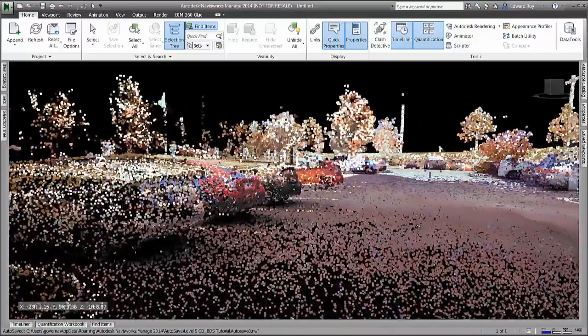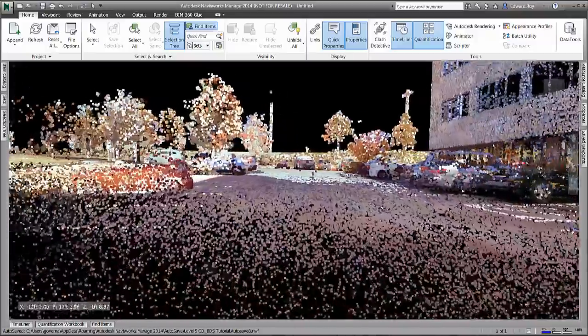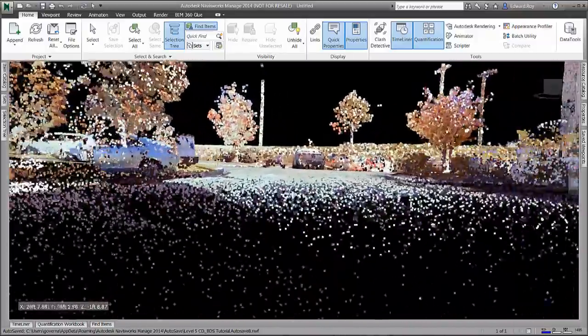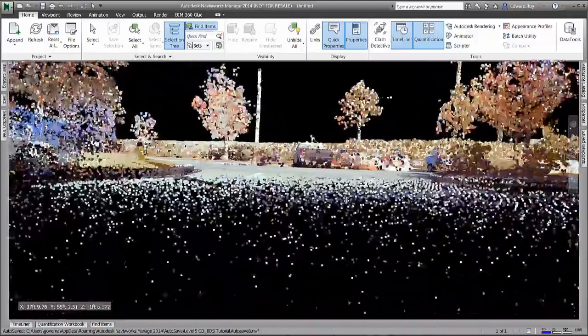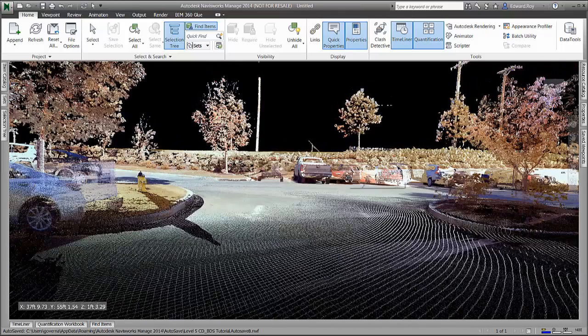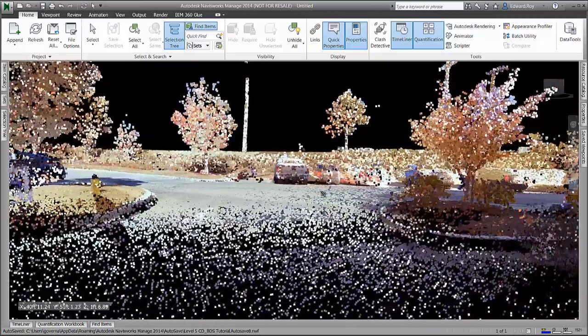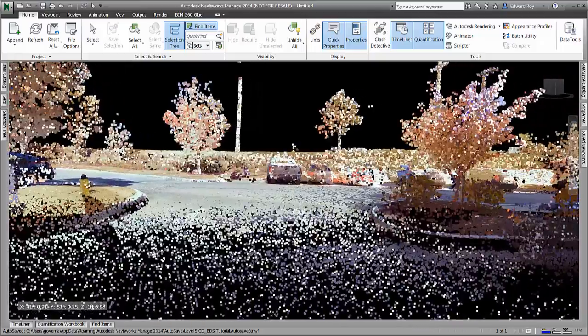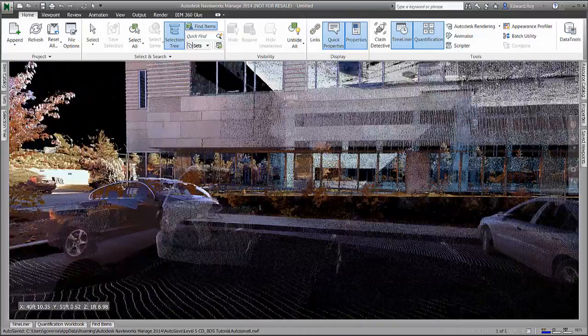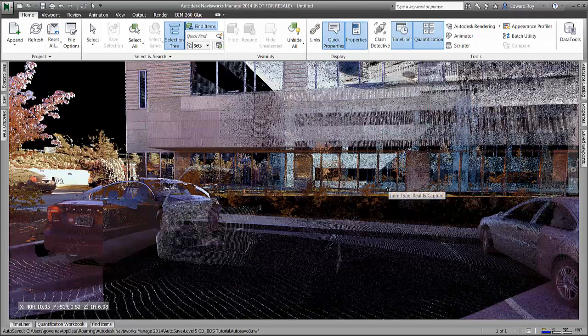So we're just using the walk tool, we're walking around, we're looking around, we're doing everything we need to. So right here in our environment that we're using as part of the Building Design Suite workflow, again, the same experience, whether it's Revit, AutoCAD, or Navisworks. You can bring in these RCP files, and that is now the native file format that we're reading for point files or point clouds and LiDAR data inside of our Autodesk Building Design Suite workflow.